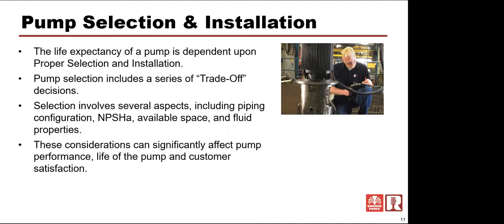If it's improperly installed, boy, you're going to have problems. You can make a pump live for 12 years, or you can kill a pump in 2 days, depending on how it's installed and put into the right type of system. Selection involves a lot of aspects, including piping configuration, what the overall configuration or available space is in the installation it's going into, what NPSH is available, that's net positive suction head, and we're going to talk about what NPSH is going forward, and what the fluid properties are.